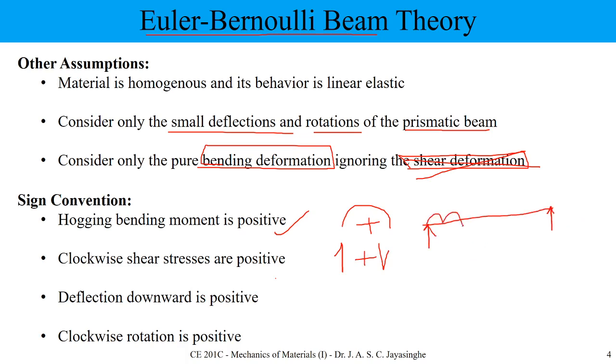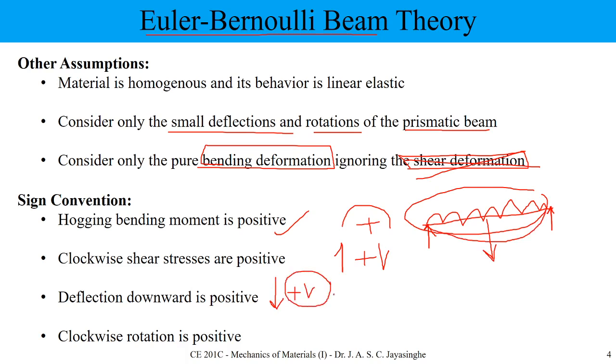Normally, generally we are working with beams. So for a beam, generally we can see loading on the top part, and we can see the deflection in the downward direction. Because of that we are using downward positive. Okay, but it depends on your textbook. If I am correct, they are using upward positive, based on their sign convention. Okay, be careful about this.